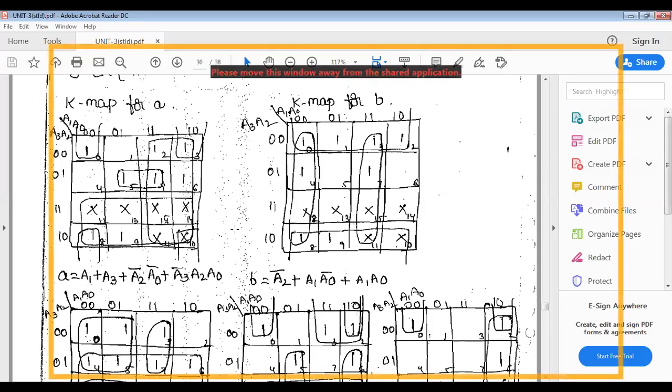After completing 5, only the minterm 0 remains. For that 0, you can see the corner bits. When you fold the corner bits, you get the adjacent sides 0, 2, 8 and 10. That is a 4 box, my dear students. 0, 2, 8 and 10.